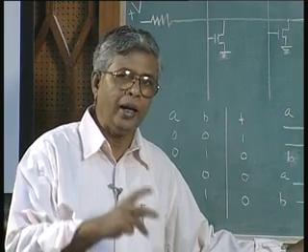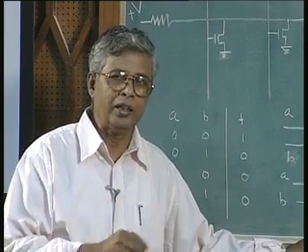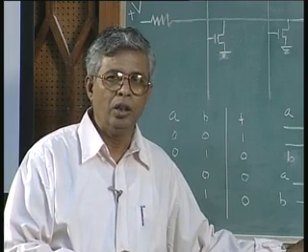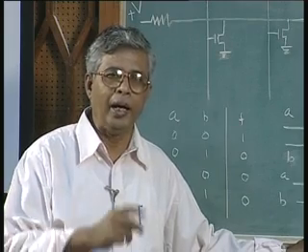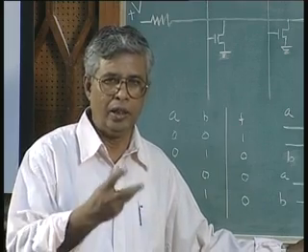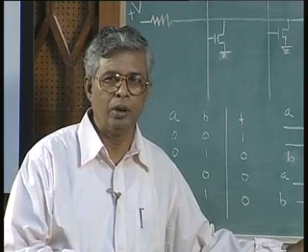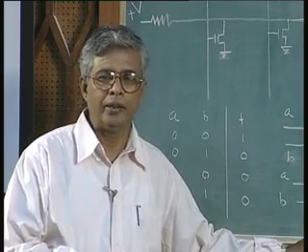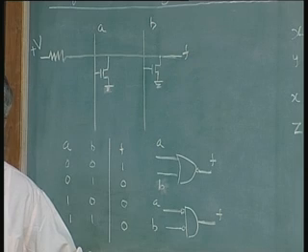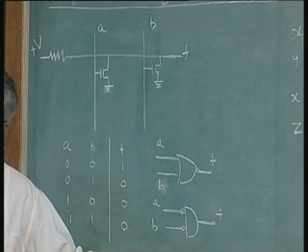Even though I drew an AND gate array and an OR gate array in the example, in practice you do not make AND gates and OR gates within a chip, within a programmable logic device chip or programmable logic array chip. There are not AND gates and OR gates. They generally use one type of gate, either a NOR gate or an AND gate.